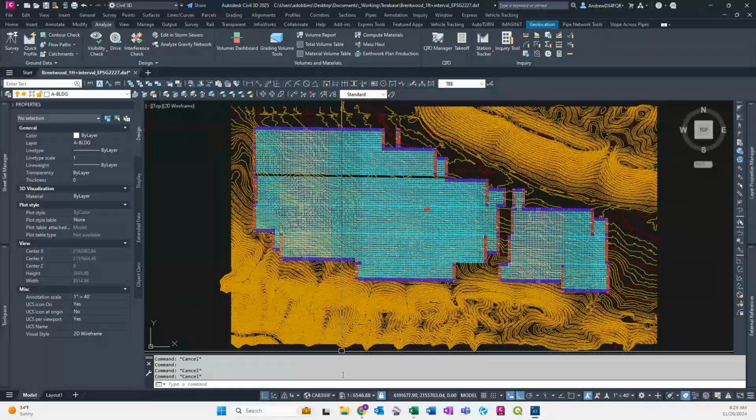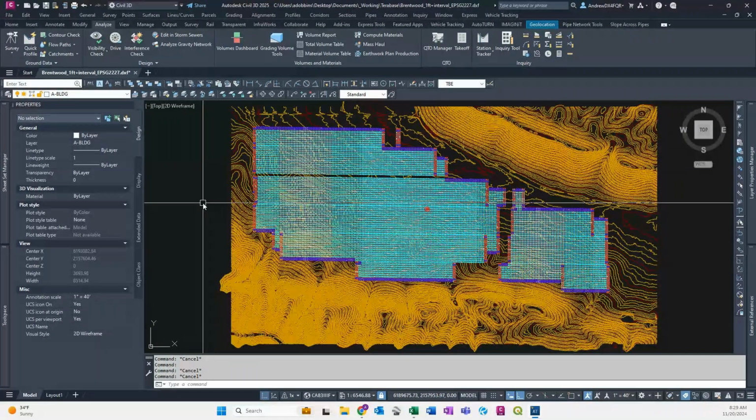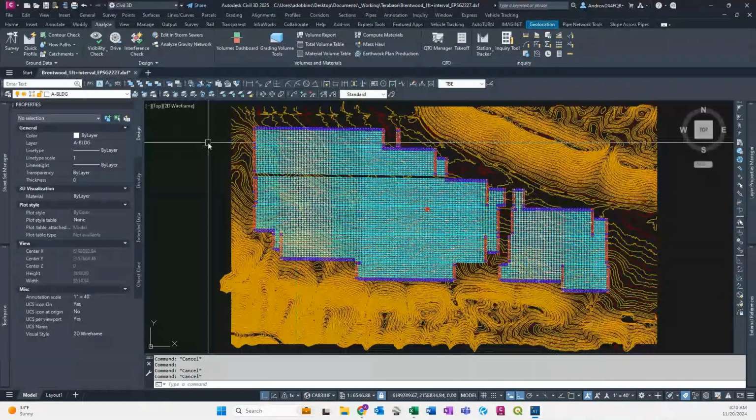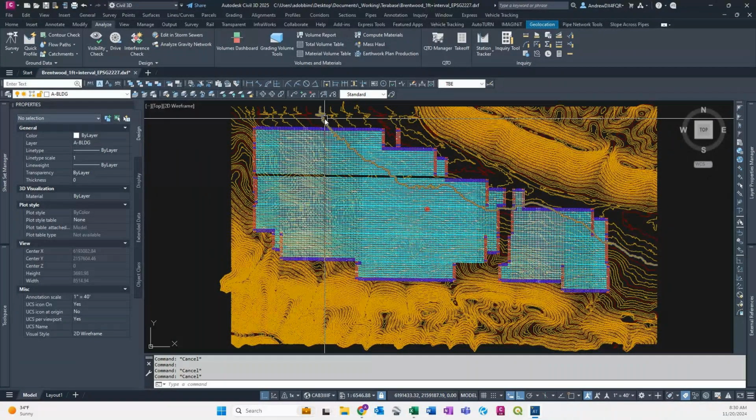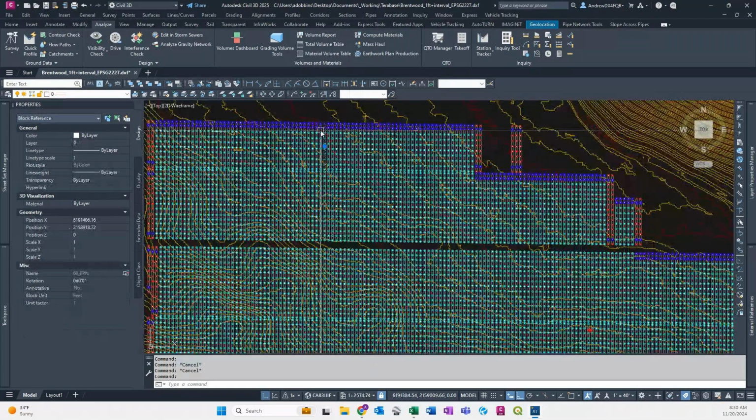And then a couple other things I'll point out that are part of this CAD file here. I have a coordinate system set up. It's important to be able to interface with the Terrain Pro software that we've got a geolocated site layout. And in this case, I'm on a California NAD 83 coordinate system. And then the third thing I'll point out that plays into the interface with Terrain Pro is the trackers that are within the layout here.